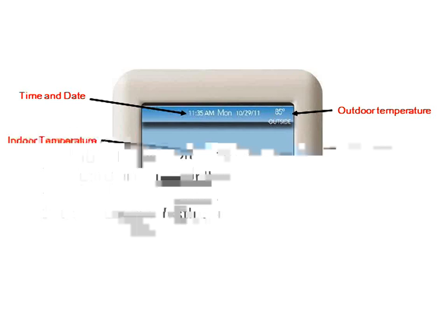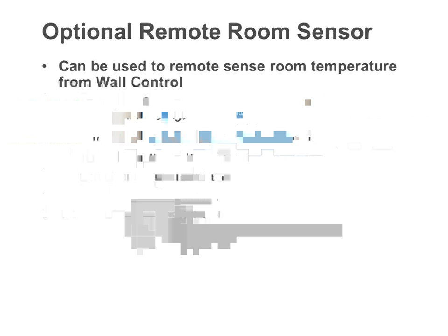And then once you do that, it'll automatically recognize that sensor, and when you're configuring the stat, it'll ask you, hey, do you want to use the local sensor inside the thermostat? Hey, do you want to use the remote sensor, or do you want to average the two of these things together? Right? So you can kind of do that a little bit to get a little better comfort in the areas you care about, but don't confuse that with zoning. It's going to make wherever the sensor is comfortable, right? It's not going to make every room comfortable, which is the purpose of zoning and what we'll talk about here in a minute.